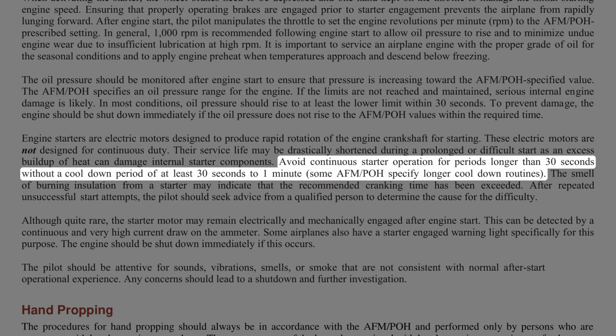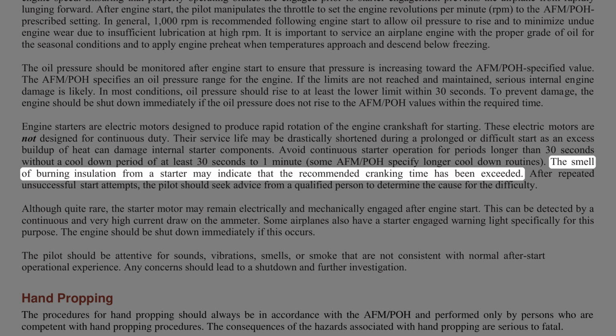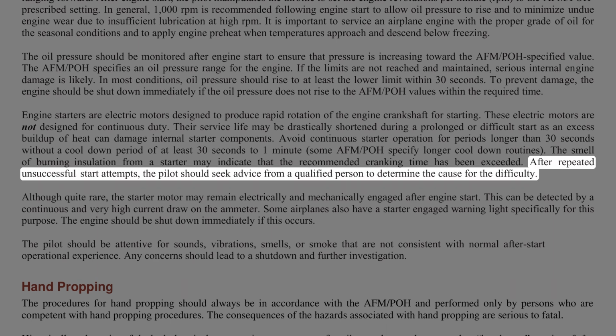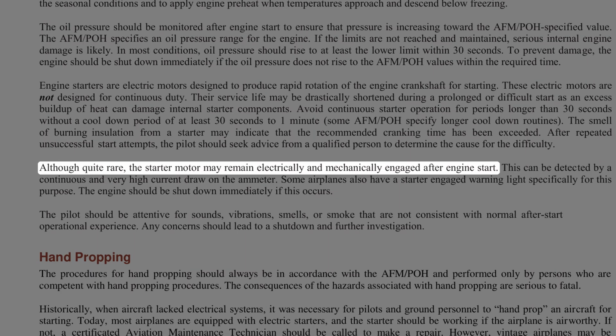Some AFM/POHs specify longer cool-down routines. The smell of burning insulation from a starter may indicate that the recommended cranking time has been exceeded. After repeated unsuccessful start attempts, the pilot should seek advice from a qualified person to determine the cause for the difficulty. Although quite rare, the starter motor may remain electrically and mechanically engaged after engine start.